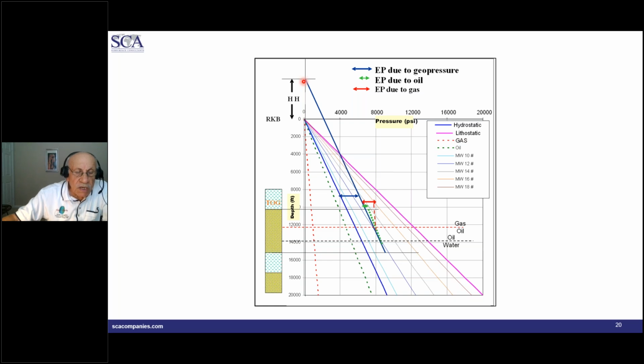That's why we have strong kicks and we have blowouts, because you have a hydraulic head. If we don't have a hydraulic head, we're not going to have a blowout, right? We're going to have strong kicks. So this is the advantage of finding hydrocarbon in the geopressure compartments. In the geopressure compartments, you can drill a well and the well produces for many, many years, just natural flow. The pressure drops, but it does not reach that hydrostatic system easily, because you have a hydraulic head.